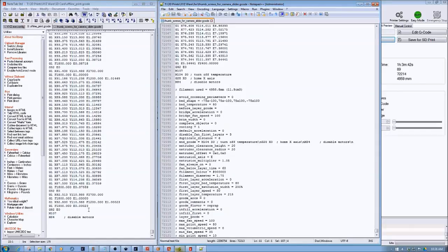So this is one of the things I have to caution. If you're going to do this, you're venturing into some potentially unsafe territory. So make sure you understand what you're doing. The other thing is this home x-axis. Slicer is homing the x-axis, where the similar G28 X0 command, I don't see it here. Again, I just see a G92 E0, and